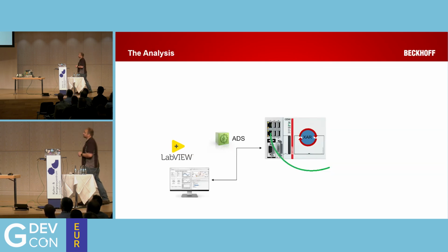So then what did we do with that? We pushed it all to LabVIEW. Okay, the customer didn't really have that much interest in learning TwinCAT programming. You can do it in some graphical languages like continuous function chart, but what they wanted really was to get it all into LabVIEW as quickly as possible and do all of the operation in there. So all the TwinCAT system did was provide a method of controlling your networks, a method of setting it all up, and then allowed them to push that data via a system we call ADS into LabVIEW.